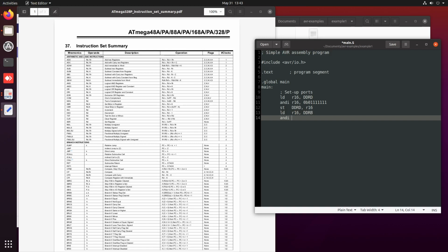In this case, we want bit number 5 to be 1. Okay, so instead of an AND, I will use an OR operation, and we will force bit number 7, 6 will be the same because we are doing an OR, and bit 5 will be 1, will be an output, and all the rest of the bits will be kept the same.